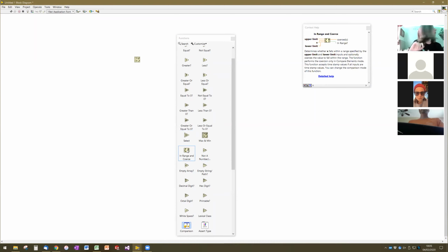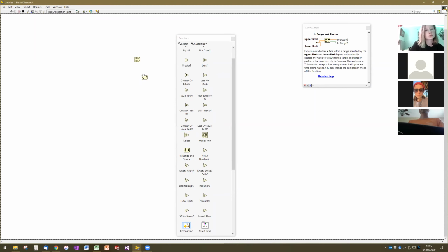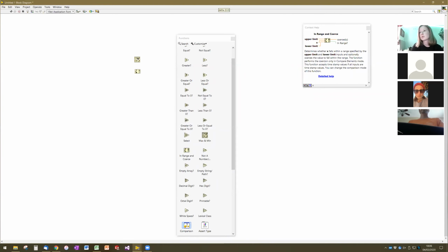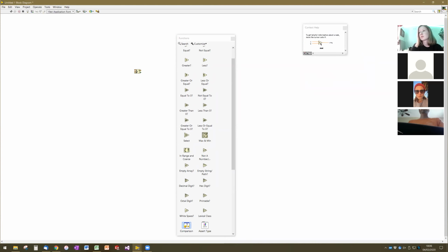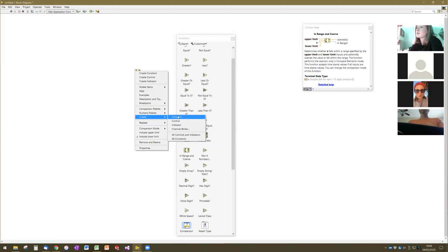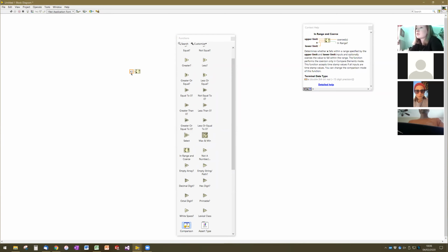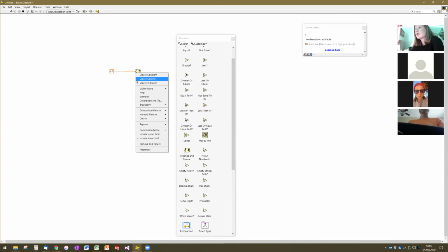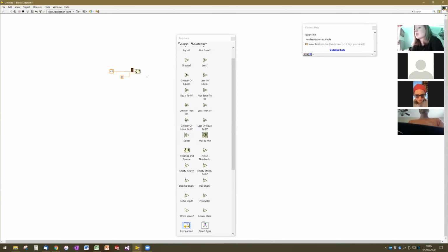And the other useful block that's shown here is the coerce block. So what this one does is you have three input terminals. You have a lower limit, an upper limit, and the number that you're checking. And so if we put in a number, and we put in a lower limit and say that the number shouldn't be allowed to be less than 0. And we're also going to not allow the number to be greater than, I don't know, 30.